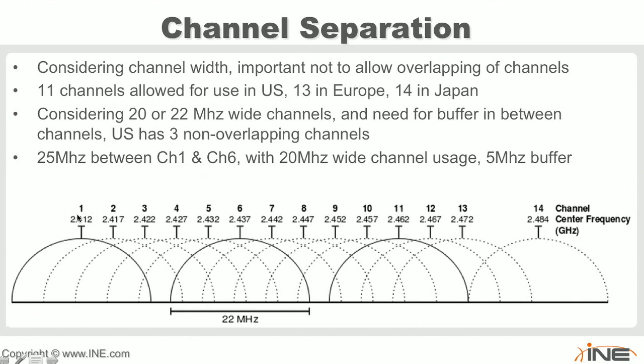Remember that channel 1 is not the bottom of the frequencies I'm transmitting at. It's just the bottom of the center channel. I'm actually using 10 megahertz below 2412. So I'm actually using down to 2402 and then up to 2422. So I'm using a 20 megahertz wide channel.